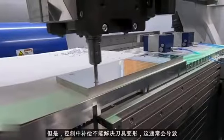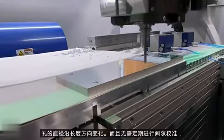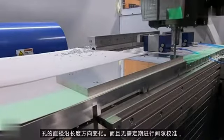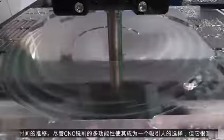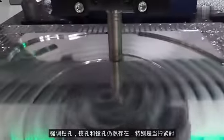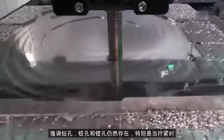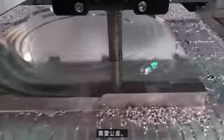However, in-control compensation can't account for tool deflection, which often causes a bore's diameter to vary in size along its length. And without regular backlash calibration, CNC mills that are heavily used tend to cut distorted circles as the ball screws wear over time. While the versatility of CNC milling makes it an appealing option, it's important to emphasize that drilling, reaming, and boring still have their place, especially when tight tolerances are required.